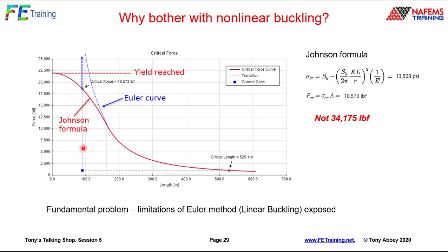Now we are deep into the nonlinear solution, so this is actually an intermediate rod or beam, and it should not be done using linear analysis. The implication of the linear solution is way up here somewhere, and the trouble with a linear buckling solution is if we get it wrong, then it's highly non-conservative. So the Johnson formula is an interaction formula basically between the Euler at that transition point and our yield point here, and here we've converted it to an equivalent force.